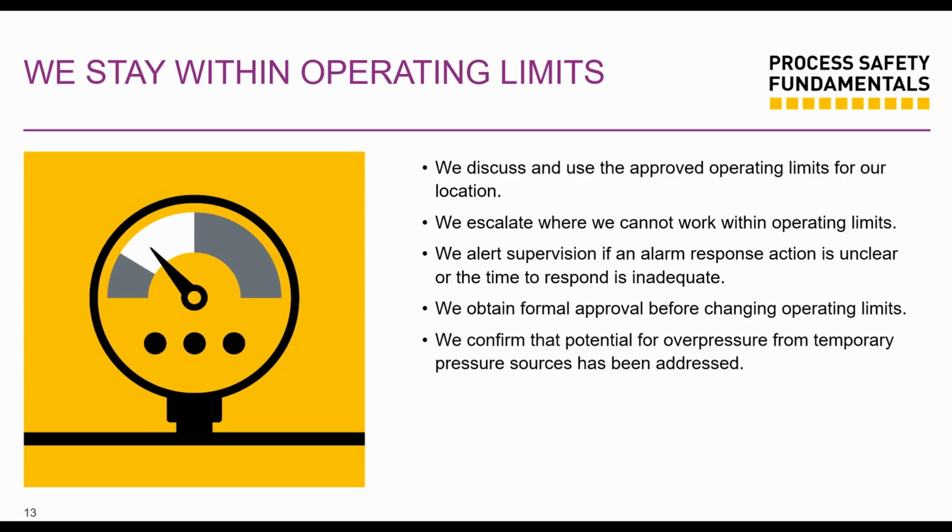We have different types of steel, different types of metal, stainless steel, that we use to build our facilities, and for some of them, there's a limit to what they can take. So make sure we discuss and use approved operating limits. If we go outside the operating limits, we're supposed to carry out an investigation. It's not only when we have loss of containment that we should be worried. So many incidents have happened, and I need to reiterate this, because of going outside of operating limits and having it normalized.